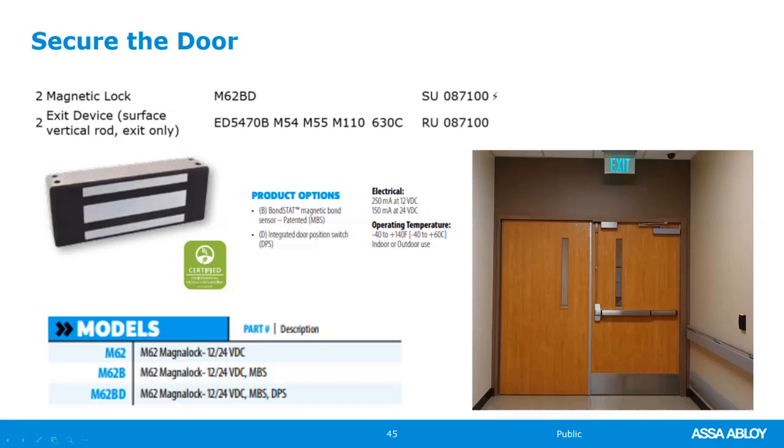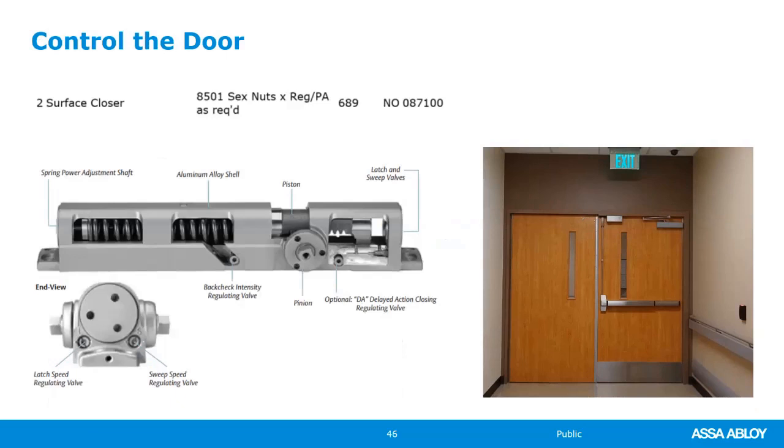And by doing so, people, if there is a fire and it's filled with thick black smoke and you can't see, you could bang your head on that. And in that case, then you would try to use a concealed shear maglock instead. Surface closer, parallel arm mounted. The spec set calls for whichever one as required. When you detail it, you would detail it as parallel arm.